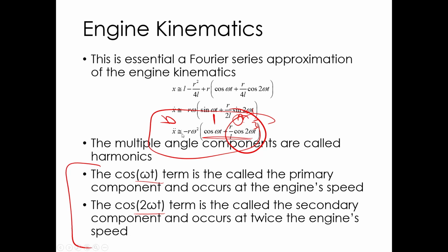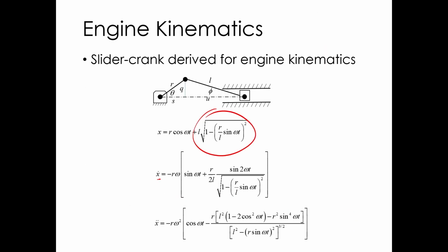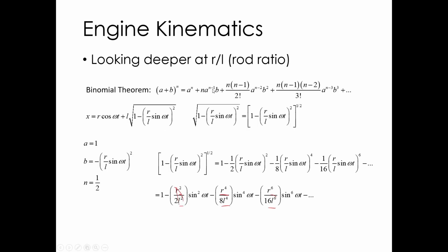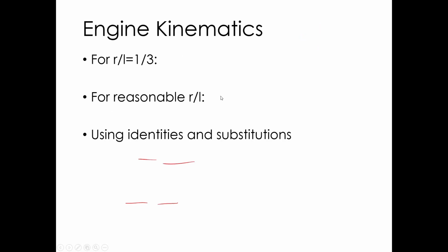So if we did this times the mass of the piston, that's going to give us essentially the component of vibrations only in way back here, only in this direction, right? We're not really talking about what's going on in this direction with the center mass of the connecting rod. So that would be another assumption in this that we haven't really covered, whether that's a good assumption or not. I'll get into a little more on how to do a better job of this in the next lecture as well.